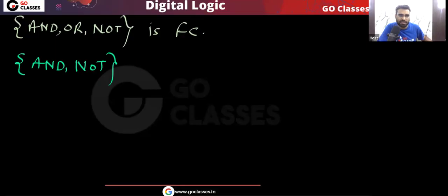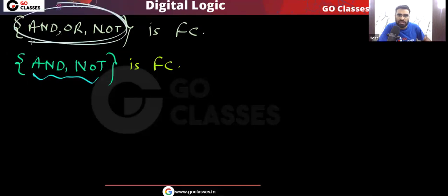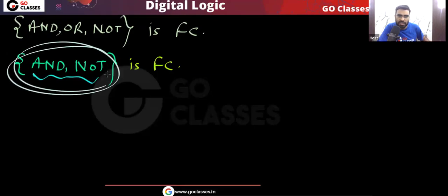See why I am saying that this is functionally complete. Because using these two, I can create OR. With the help of AND, NOT, I can create OR. Is this clear? Already I have AND, I have NOT, and with the help of these two, I can create OR. So overall, I can say that I have all these three. Yes or no? If you give me these two, then I can create all these three, and I can write expression of any Boolean function.